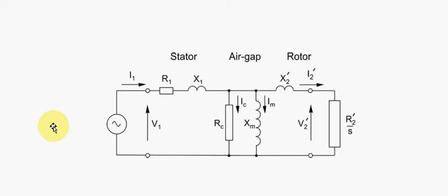So here in front of you, you have the motor equivalent model. This represents a single phase of the motor, and so that would be the supply voltage over here, and this is what we're varying: this voltage, amplitude, and frequency. And these values here are the various values knocking around that motor. Okay, the value that we're interested in is actually this IM value, and this magnetizing inductance value over here. Now this is the guy responsible for setting up the flux in the air gap.